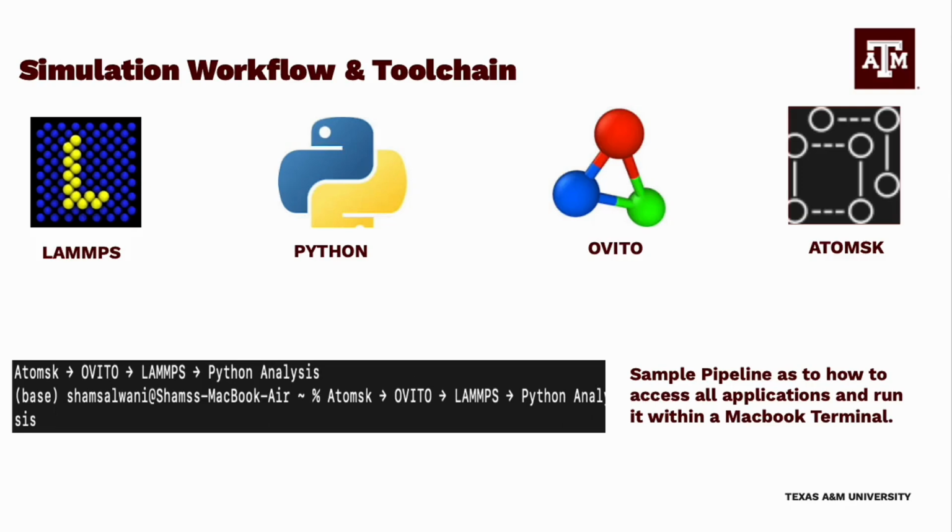I ran three types of simulations: cooling systems to capture temperature-induced phase transformation, uniaxial compression to simulate stress-induced transformation, and mechanical cyclic loading to reveal memory and fatigue behavior. OVITO was used extensively to visualize phase structure and identify dislocations using the dislocation extraction algorithm. The result is a multi-scale view of transformation and damage, ranging from overall stress-strain behavior down to individual atomic rearrangements.